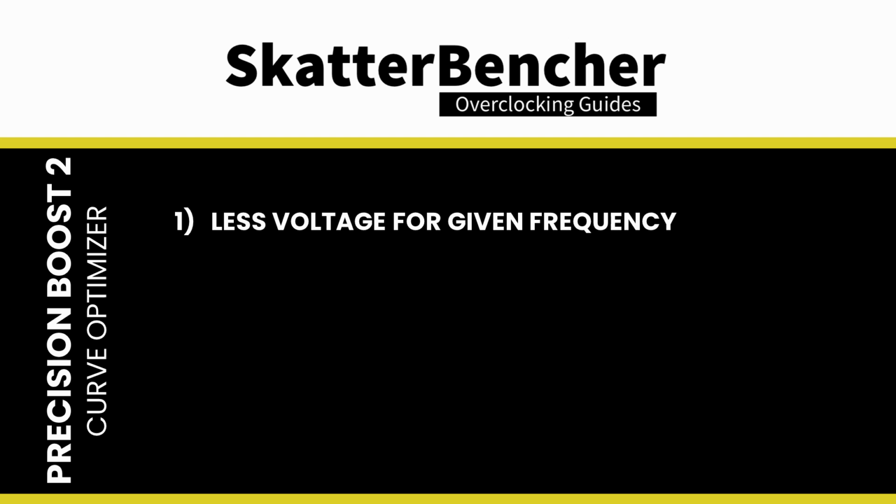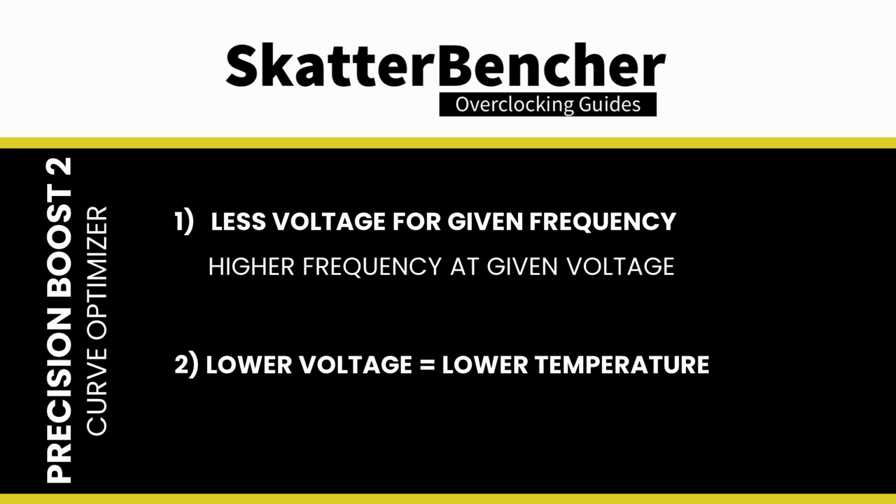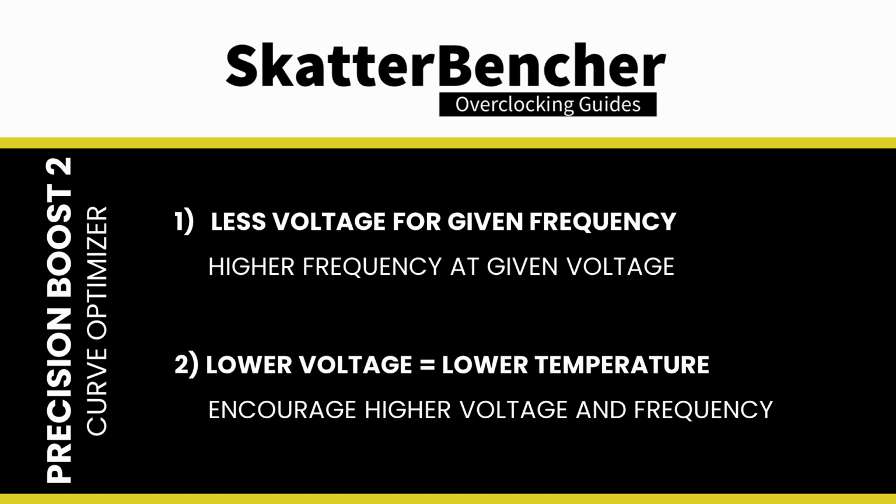The traditional approach to AMD Ryzen CPU overclocking is by configuring a negative curve optimizer setting. Two things happen when you do this. First, you effectively tell the CPU that it needs less voltage for a given frequency, and as a consequence, at a given voltage, it can apply a higher frequency. Second, the CPU temperature will be lower because you use less voltage at a given frequency. That extra thermal headroom will also encourage the precision boost algorithm to target higher voltages and frequencies. Now to get back to that -300 curve optimizer.